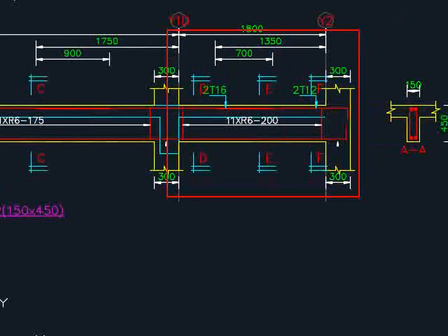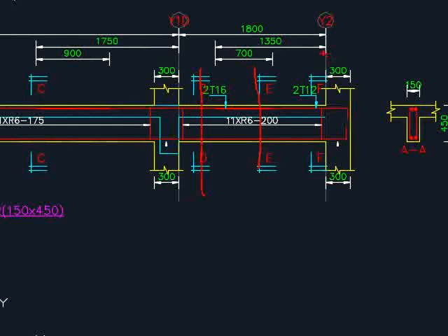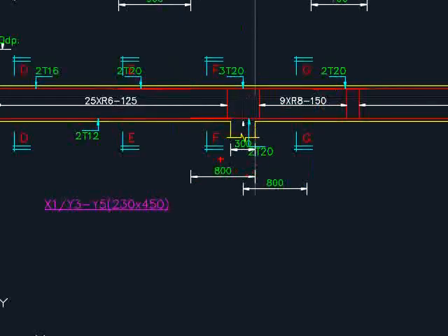This is another example. What you see here, there are 3 cut sections, which in fact is not necessary. Even though you do these 3 cut sections, they are actually the same shape in the cross section. You can remove the redundancy in order to keep your drawing neat and tidy. There is a lot of overlaying text which you need to remove so that there is no ambiguity with the drawings or unclear text. Same goes to this and this.